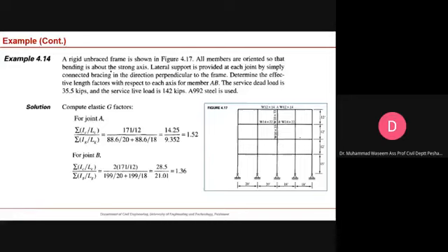So now we have to use these inelastic or elastic formulations to calculate the effective K factor for a column, which is a part of this frame. There is a column which is column A to column B, okay? Now we have to compute GA and GB value, okay? We have to compute it for the elastic case first, and then multiply it with the tau. Now for the joint A here,